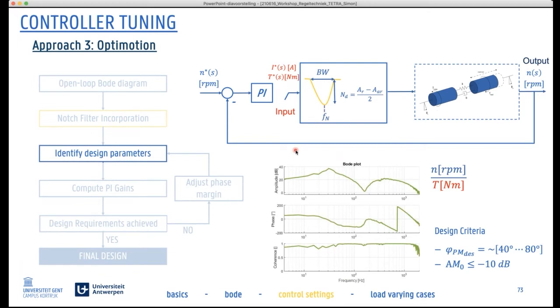How will we do that? Well, we do it step by step. We go first to the point at which we have a phase of minus 180 degrees. That's also the point at which you have this shift, because actually that point and that point only differ 360 degrees, in geometrical terms that's just the same. So you start by identifying the point at which you have minus 180 degrees. That's the point at which you have the shift.